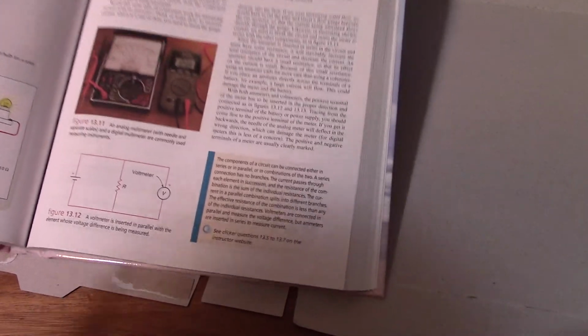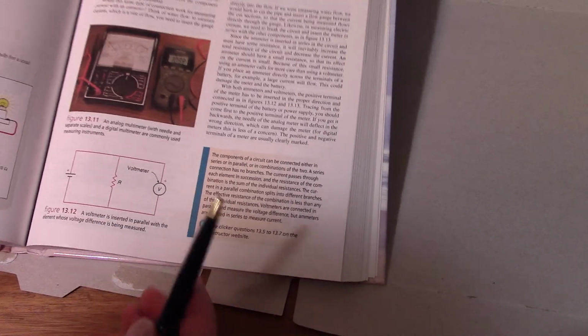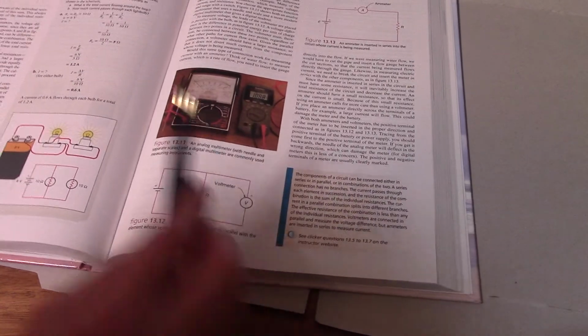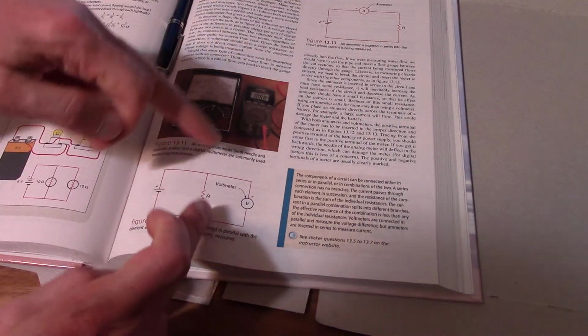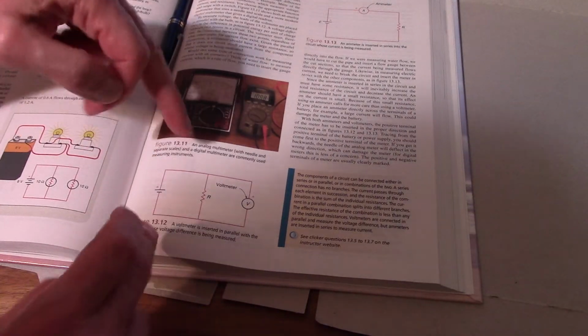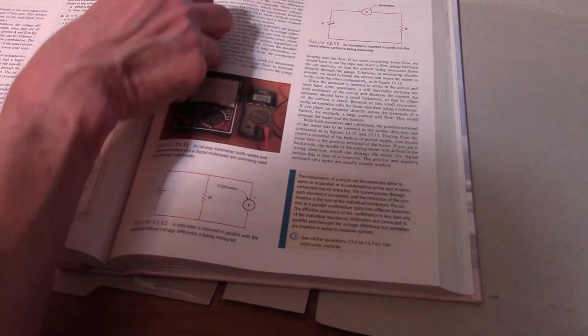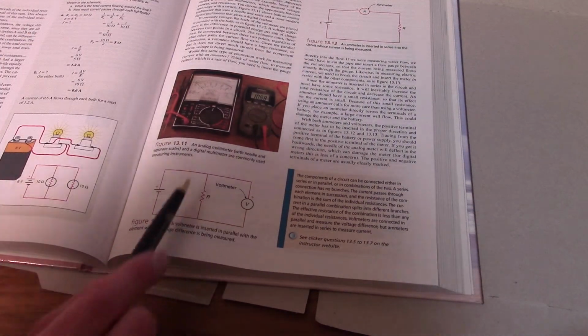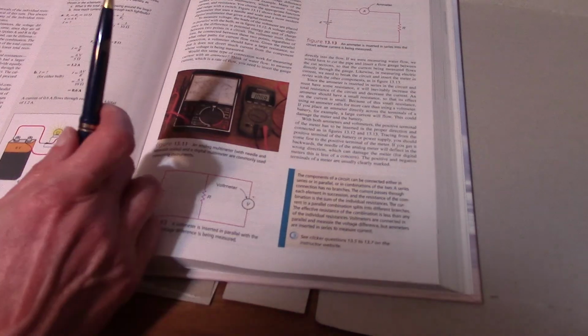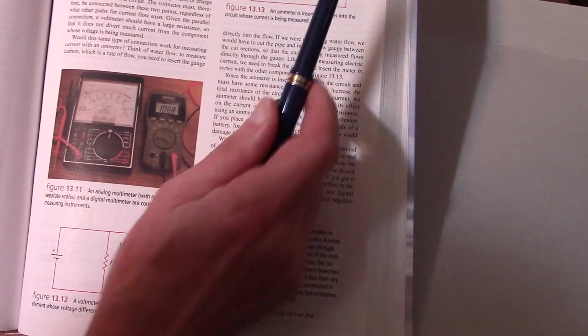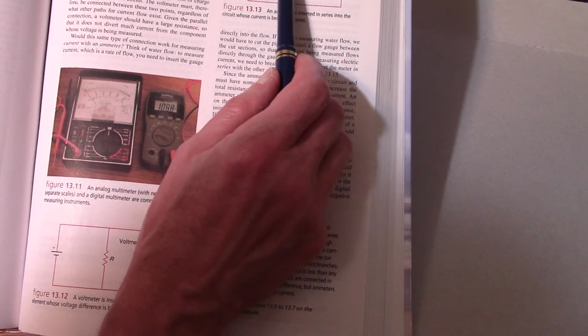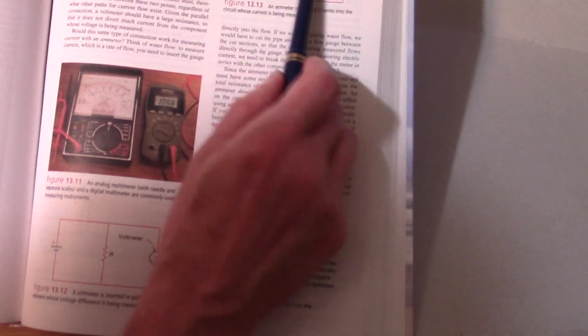These pictures are here again. Measuring a voltage, right? So a voltmeter is a device where you would measure voltage. Here you measure it across the battery. No current is going through the voltage meter, but it's measuring the voltage. In order to measure the current, there's two types. One, the current actually goes through the meter. So it's measuring those little electrons going through it.